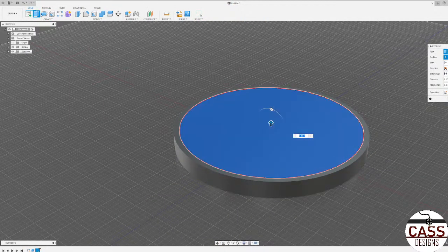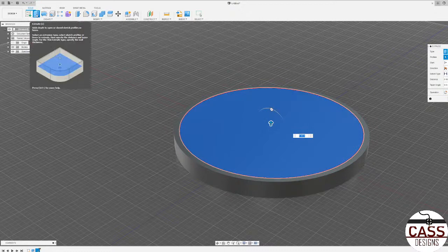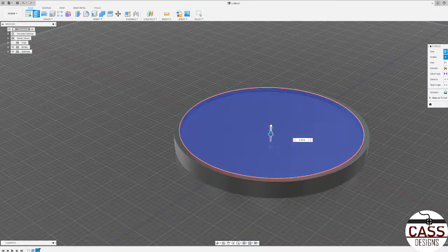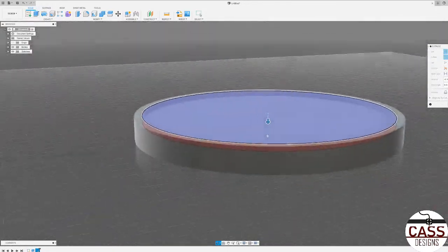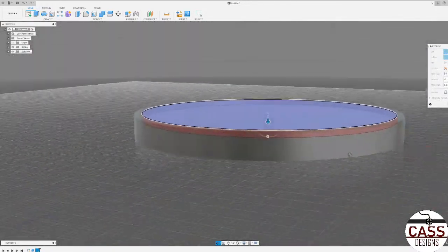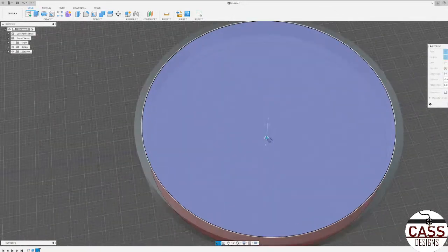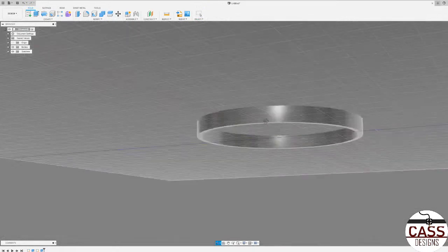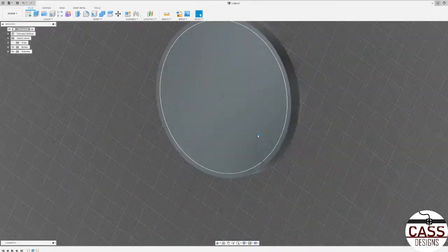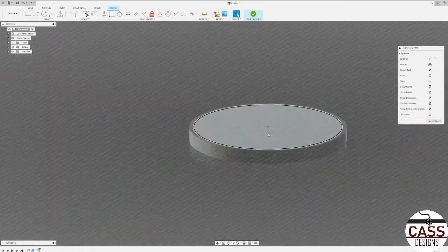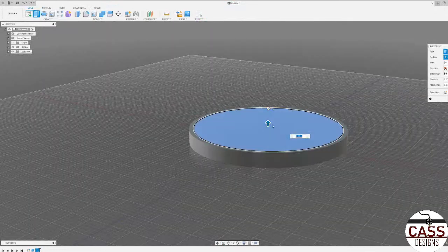But in Autodesk Fusion 360, they kind of use extrude to cut and extrude. And you'll see what I mean. I can drag downward, and it kind of makes this volume red. And that means that it's cutting it and getting rid of it. We can go all the way through to just make a ring. As you can see here now, there's nothing on the inside. So I press Control Z to undo that. Going back, we can click this again, and then click E again.